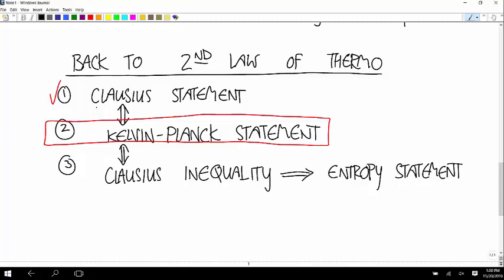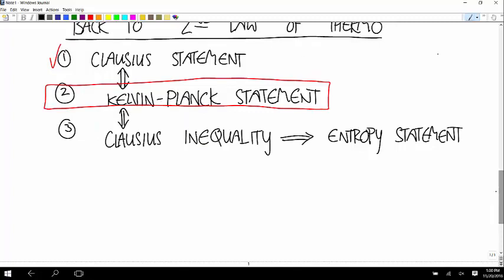So it turns out that if you have a heat engine with a boiler of 500 Kelvin and a condenser, the cold reservoir, of 200 Kelvin, there's a theoretical limit. If you have no irreversibilities in your system, there's still a finite limit on the performance of the power cycle that you can get out of that, or the refrigeration cycle, or the heat pump cycle. So that's what we're doing now. We're sort of working towards that. And I just started talking about performance of cycles.